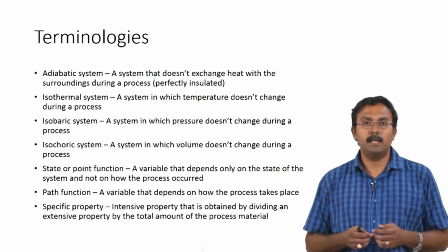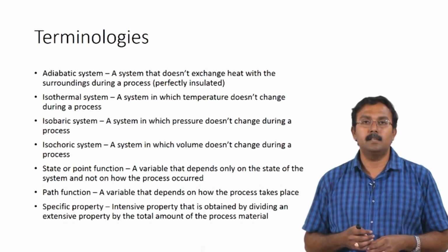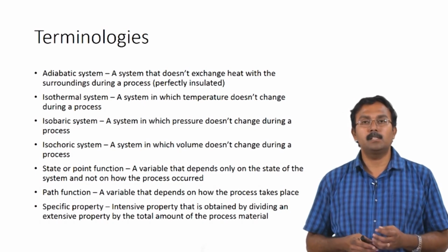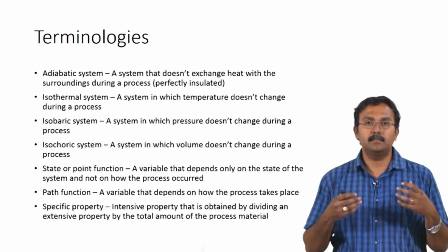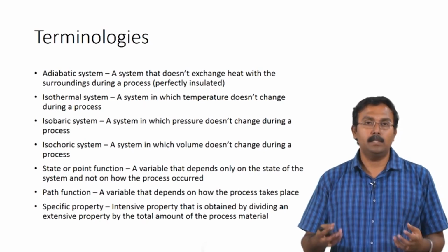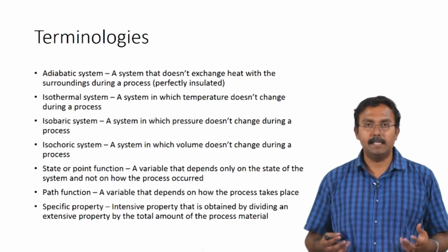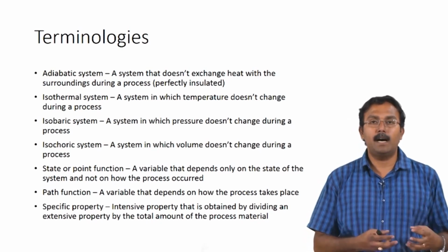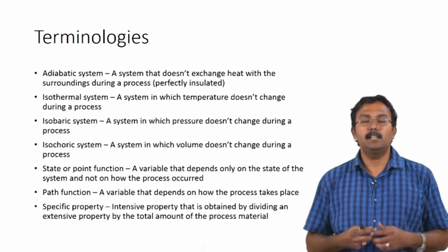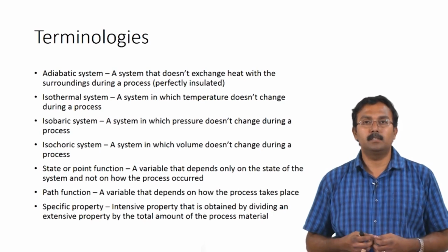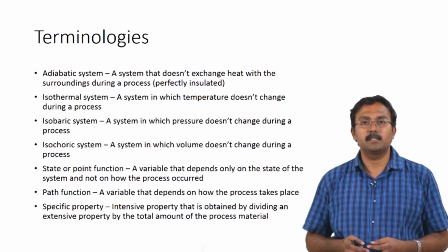So, when we use the steam table, you would see the specific volume, specific internal energy and specific enthalpy listed, and this is possible because it is not dependent on the size of the system, and it is only given as a specific property. We can take these values and apply them while we perform calculations for systems of any size. And when we multiply the mass or number of moles of the component by the specific property, we will get the total value for these components. So, this is really useful while we perform calculations.